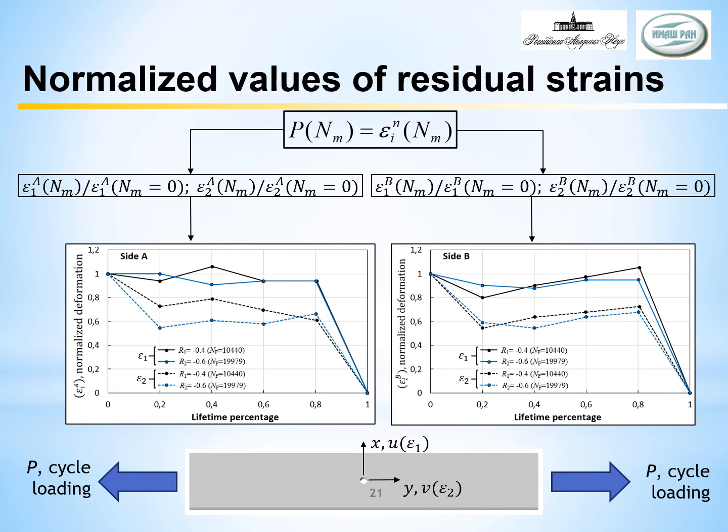Values of increments of secondary hole diameter in principal stress directions were obtained at different stages of low cycle fatigue. These data assure construction of normalized dependencies of the damage parameter against lifetime, which provide the explicit form of the damage accumulation function.